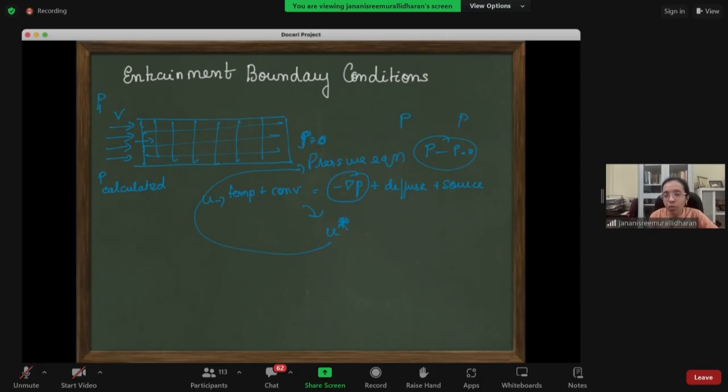So typically this kind of equation is going to crash. Ideally you would need a velocity to push through, but the pressure at the inlet boundary is not fixed, so that it can iterate based on the outlet pressure. That's the flexibility you want.